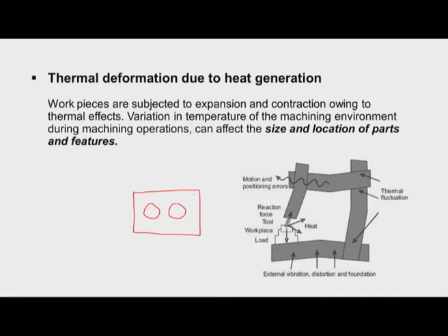Now, because of the milling the workpiece is in a heated condition, and immediately it goes for the drilling operation. So, he puts the drill and there is some tolerance for the center distance. Now, once the drilling is over the workpiece is removed, and then when it cools because of the contraction the center distance may change. So, like this the dimensional changes will occur, and also the vibration from other machine tools or other operations.